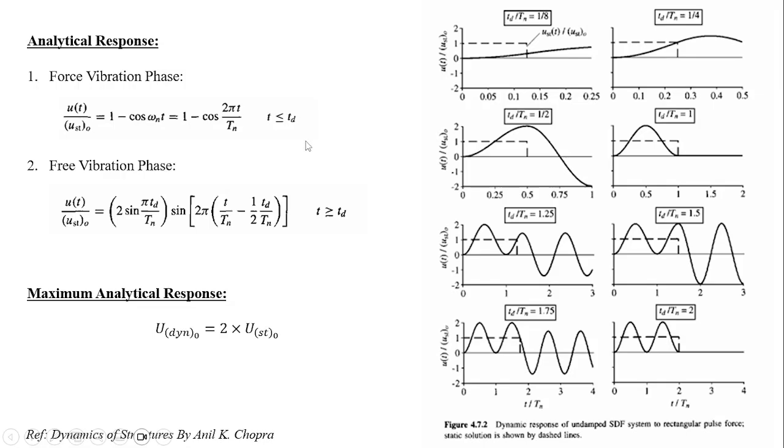And after that, when we stop the force, there is no force working on it, but due to the effect of the previous force, there exists a free vibration phase. The response during the free vibration phase, which is t greater than td, is given by this equation for the SDOF system. He used these two formulas to plot the graphs shown on the right.